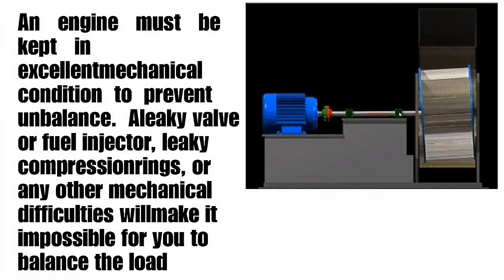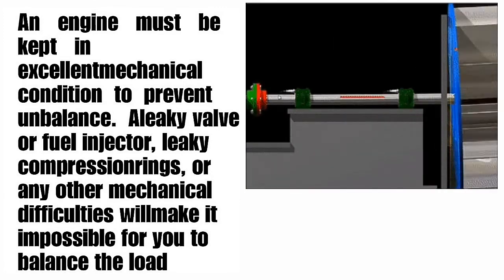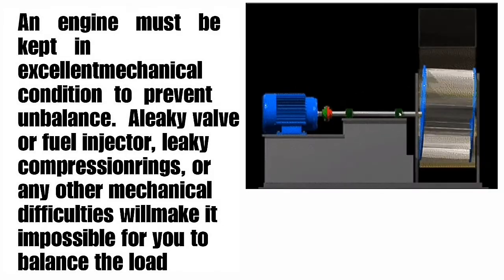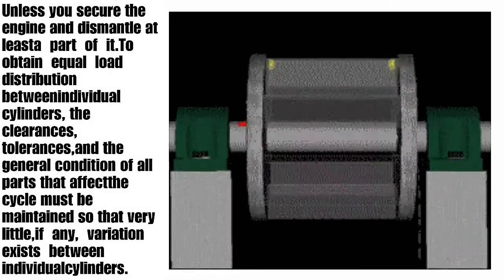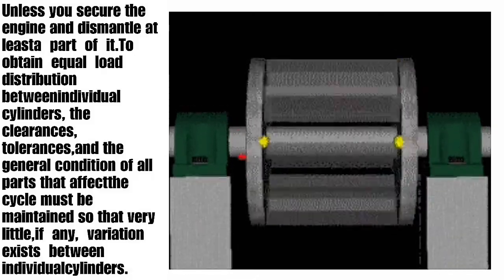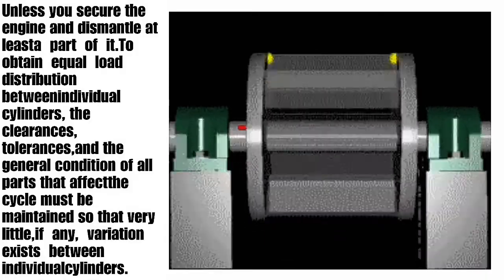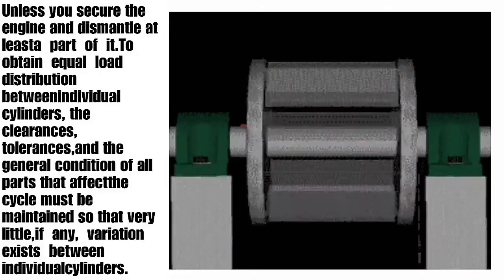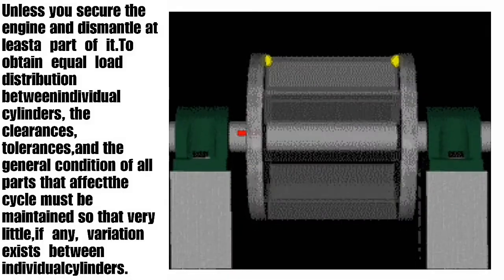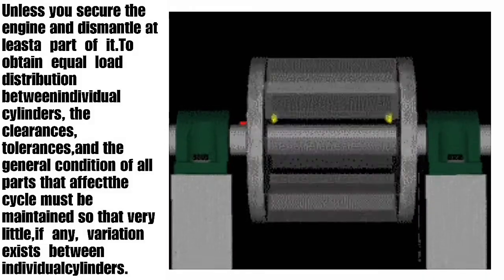An engine must be kept in an excellent mechanical condition to prevent unbalance. A leaky valve or a fuel injector, leaky compression rings, or any other mechanical difficulties will make it impossible for you to balance the load, unless you secure the engine and dismantle at least a part of it to obtain equal load distribution between individual cylinders. The clearance tolerance and the general condition of all parts that affect the cycle must be maintained so that very little, if any, variation exists between individual cylinders.